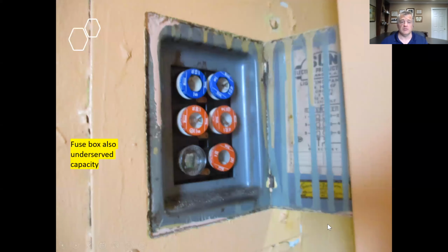We also see fuses. Replace them. There was a time even in my career where it was okay to keep them, and we put in these tamper-proof inserts so you could only put the proper amperage in, so you wouldn't fool it into not tripping. But now we know that it's got to be at least a certain number of years old to be a fuse box. Replace it with breaker switches.